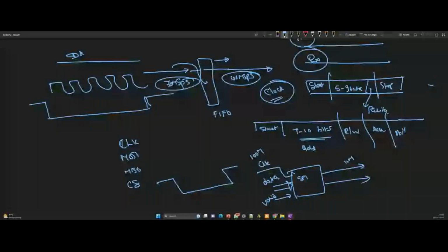For example, you are choosing one ADC IC which is integrated to your FPGA. Whatever interface that IC follows, you have to talk to it with that interface, right? The IC designer has chosen that interface, so you have to use it. The interface is like a communication language, right? If that guy knows only Chinese or only Korean, somehow we have to translate into Korean and communicate with him. The same way, if that guy is capable of reading only I2C and internally you have some SPI, somewhere you should have a translation so that he can understand. If he is understanding only I2C, then we have to make it work like I2C itself.